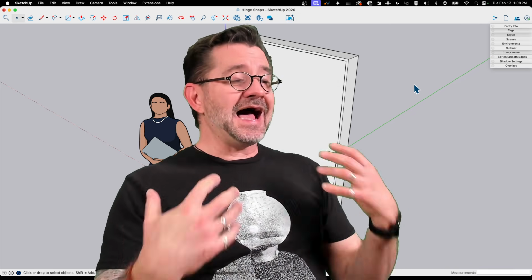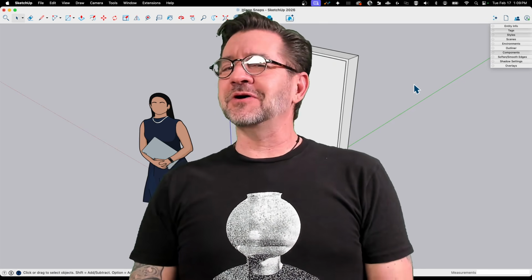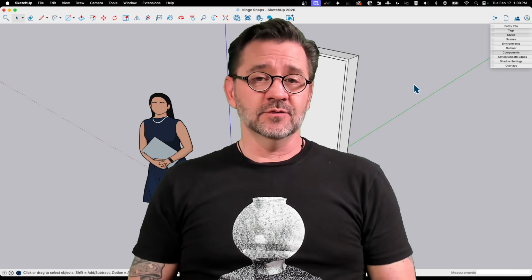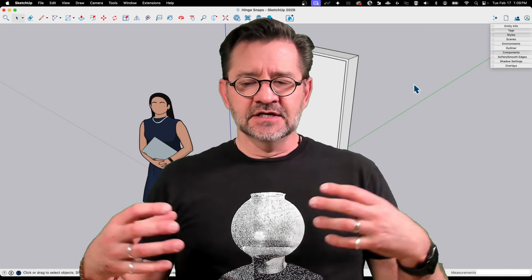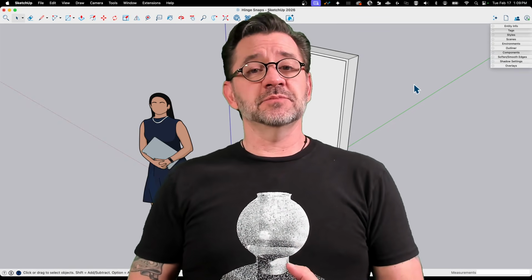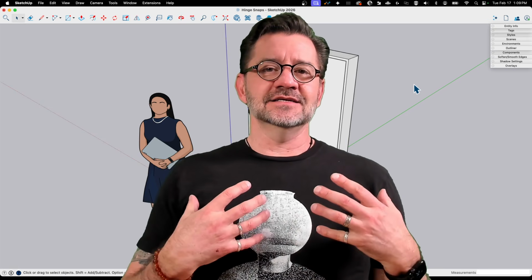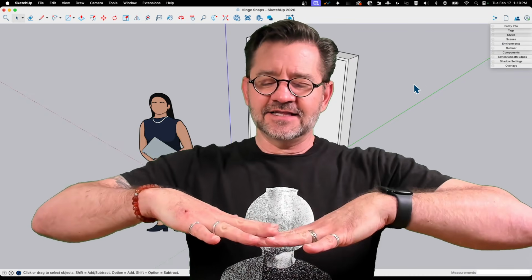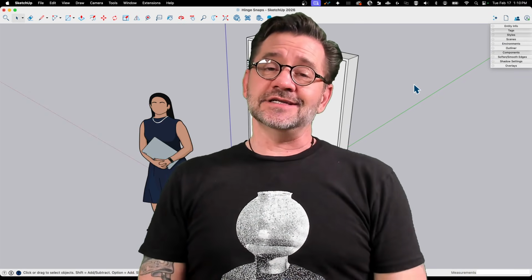So I'm a big fan of having an existing tool and finding new ways to use it. How do you get the most out of the tools you already have? And this is a perfect example with snaps because, yes, snaps can be used to connect things together, and that's absolutely true. That's a big part of what they work for, but they also work as user-defined snap points. And by putting that point in there, by making it flat this way, we know we're always going to rotate around that flat. It's just a quicker and easier way to do it.